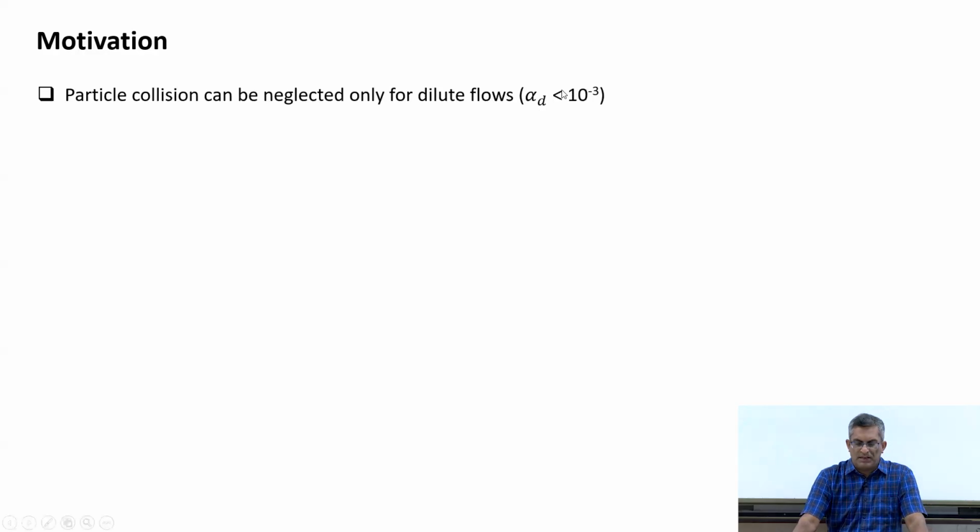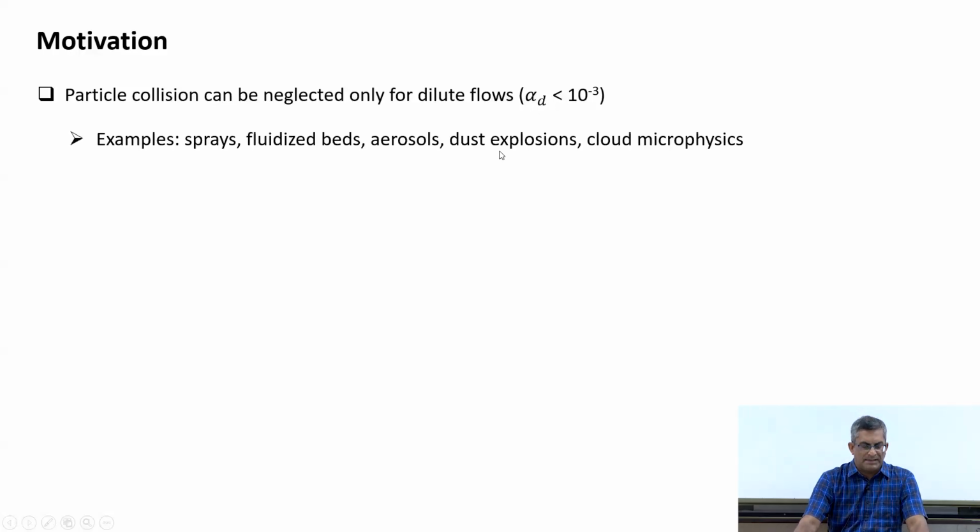But it can be shown that when we have volume fraction of the order of 10 to the power minus 3, then collisions become more frequent, as in these examples. For example, sprays especially close to the injector exit, fluidized beds, aerosols, dust explosions, cloud microphysics. So, in all these cases collision plays a very important role in the evolution of the particles.